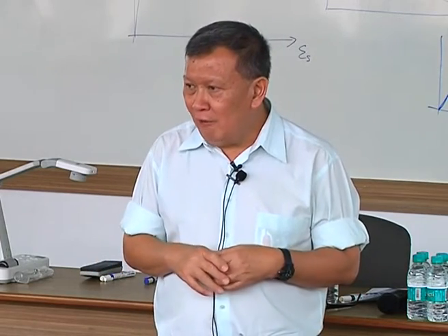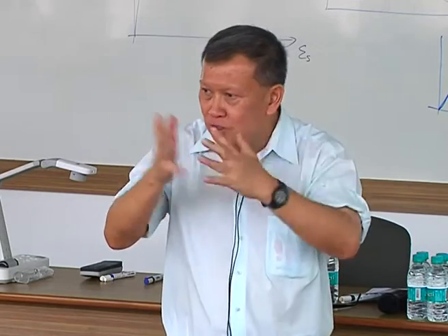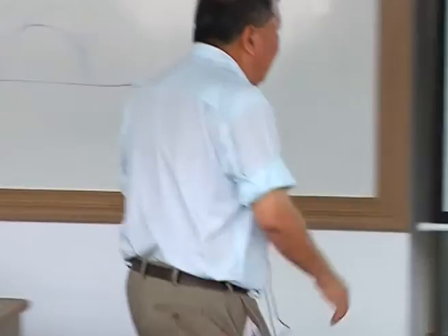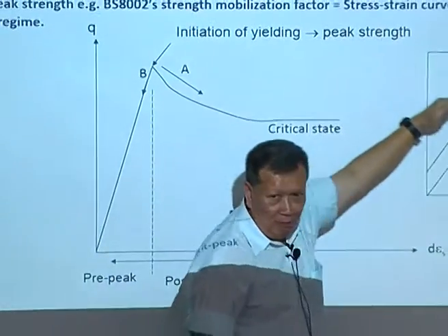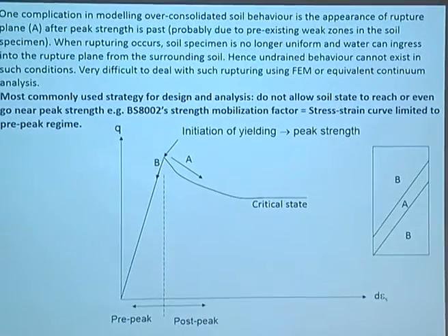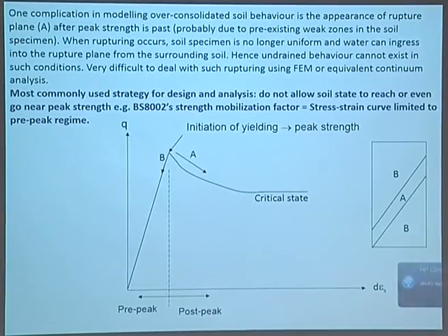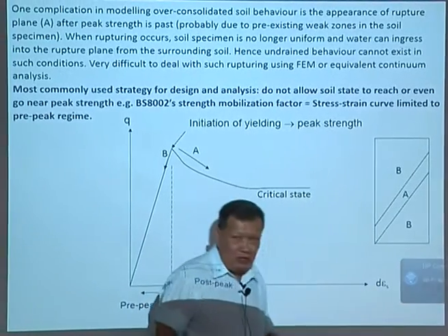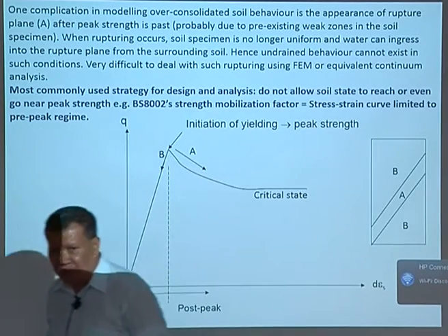Okay, instead of a big shear band going like that, you get diffuse shearing, and your stress strain curve, instead of having a sharp drop going down like that, in an undrained situation, you get a very gradual drop going down, which I think is more representative of the real situation. Okay? Because once your shear band starts going, then the strain here can build up very rapidly. Externally, you may measure a strain of 20%. Internally, this could be a few 100% inside the shear band. Okay?